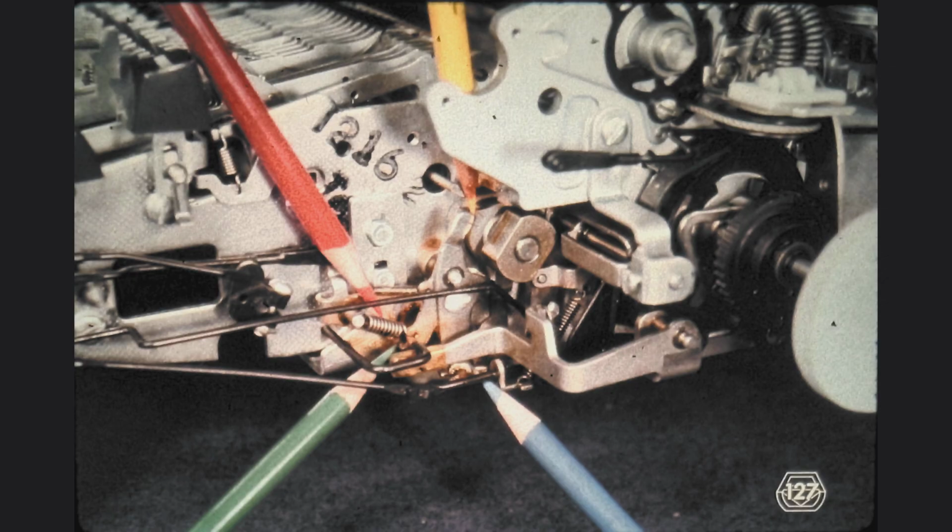When the whole mechanism is at rest, as shown, the front-to-rear clearance between the selector latch and the cam follower at the point indicated by the green pencil should be approximately 1/4 of 1 millimeter. If this clearance is too large, the cam follower may rotate too much during high-velocity character printing operations, pulling on the velocity control cable, at the blue pencil, during cycles in which the cable should be left undisturbed.